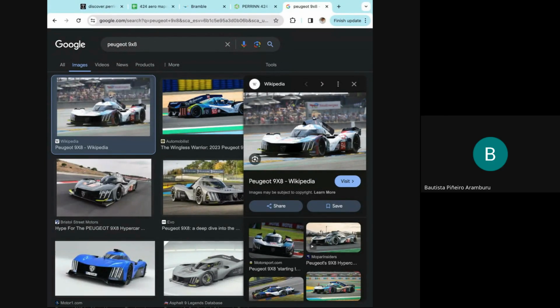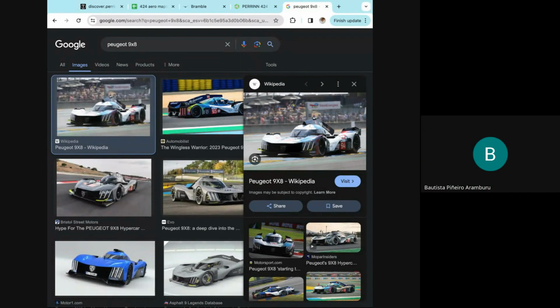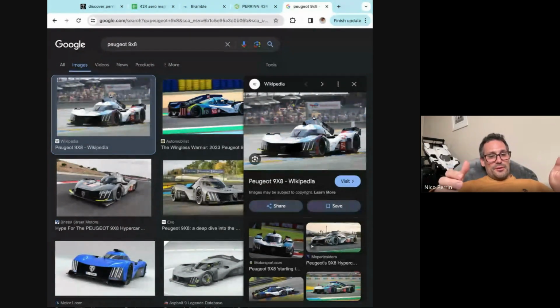It's the same for aerodynamics concept. You will not actually find a lot of examples on 424, because there's only, for example, one dive plane at the front, under the front wing. Some people put 3 or 4. If somebody would come to me and say, instead of 2 dive planes or fences under the front wing, I've put a bigger one, a single one, and the performance is the same, I'll say, let's go for it. Then I know we've got less parameters, and less parameters mean we can do bigger tests where we move one bigger geometry and the sensitivities will be bigger, and then we'll optimize that to a higher performance level before we add more complexity.